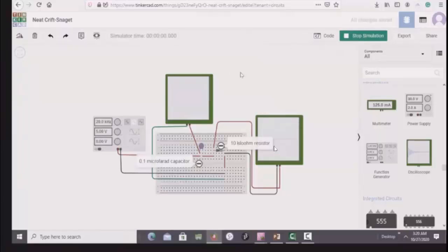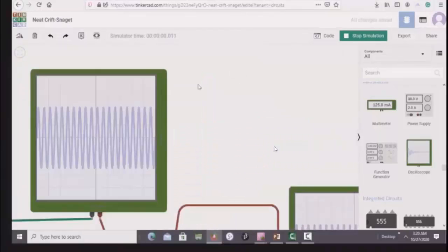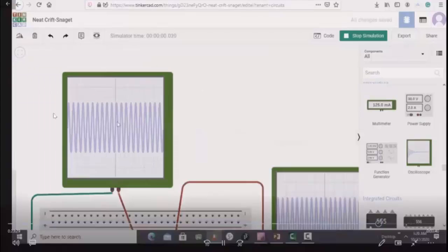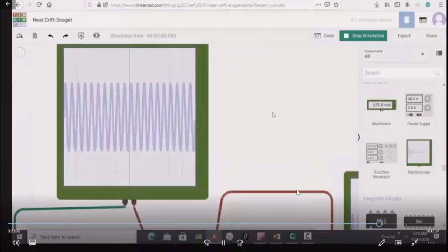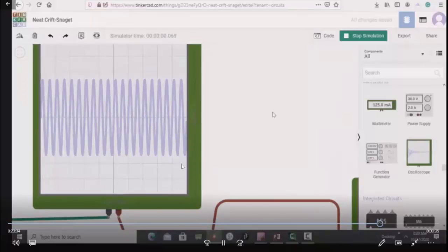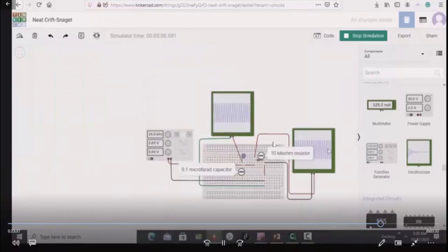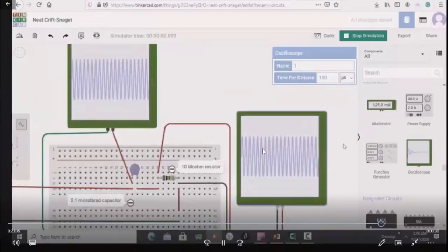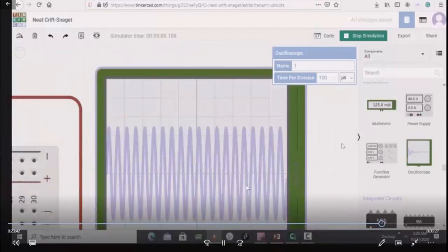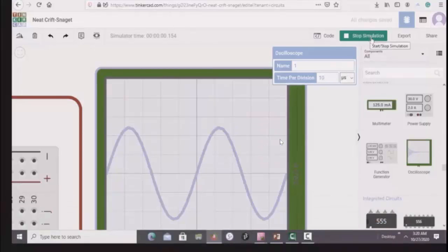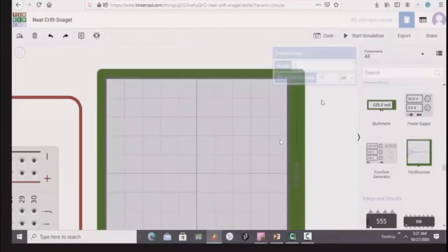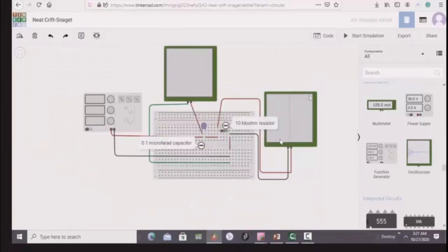And you can see now that if I go on increasing the frequency, the value of the output does not change. This is 5 volts, and this has already reached 5 volts. This is close to 5. So you can see it's 2.5 squares on either side. And on this particular CRO, this is 10 volts, and this is also almost 2.5 on either side. So it has reached the flat part, and I can change the time per division so that I get one complete loop here on the CRO, and I can find out the peak to peak values.